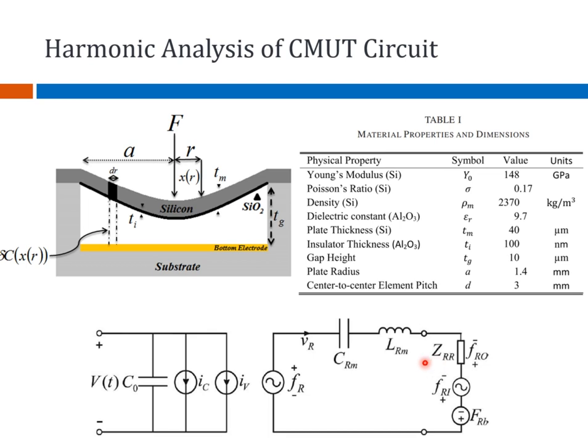Okay, so this is the model, but this model does not include any loss except for the radiation impedance. And if you do not include any other loss like substrate impedance, well, what you have is once you simulate these dimensional parameters, since the lumped components are defined in terms of these dimensional parameters, you can go and have a look at the literature for how these lumped components are defined in terms of those parameters.